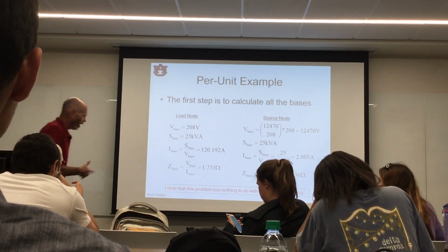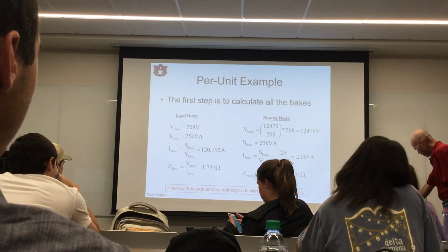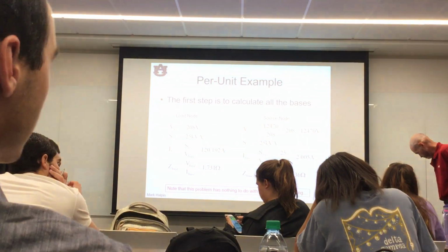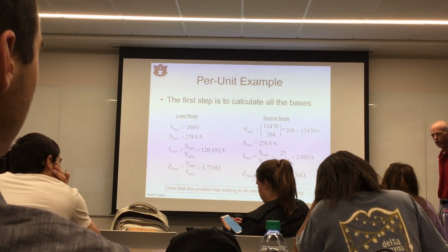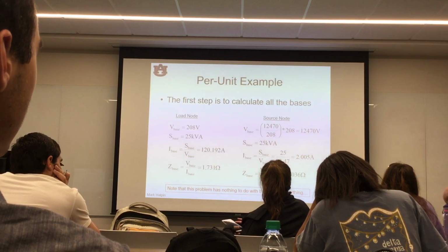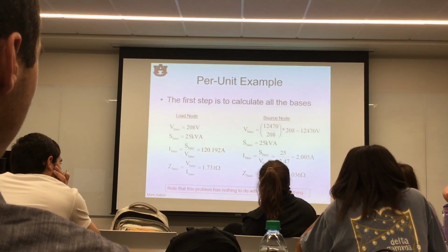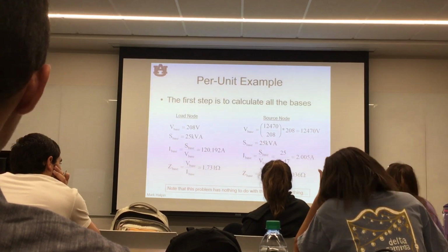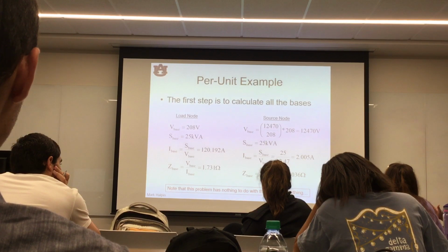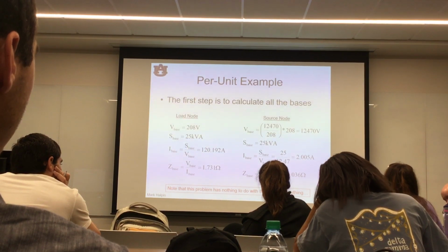If I'm thinking, well, let's see, I want to talk about the voltage of that outlet right there. Well, we all know that ought to be somewhere around 120 volts. If I ponder that voltage and want to talk about it in percent, well, if it's a little bit low, maybe 114 volts, I still run my computer.